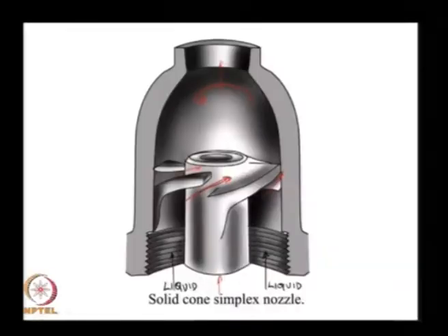disc-like distribution. Okay. So, in this particular design, it is more likely that you are going to have drops in the middle. Now, because of the way the simplex part of this nozzle works in relation to the pressure jet part of the nozzle. So, this is more like a pressure jet spray, and this part is more like a simplex spray. Because of a combination of these two, the drop sizes coming out of the pressure jet are going to be generally larger than the drop sizes in the simplex spray.